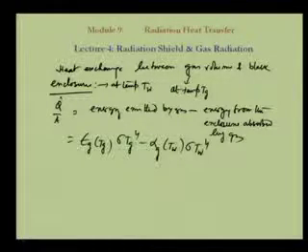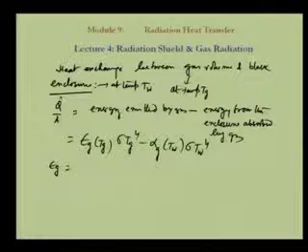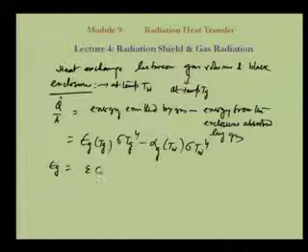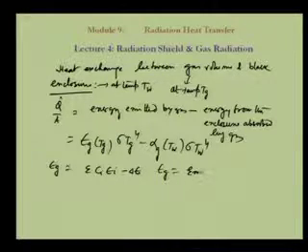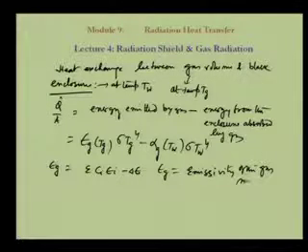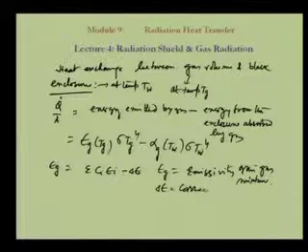Now, emissivity epsilon g is calculated as summation of C I epsilon I minus delta epsilon. What is this? This epsilon g is the emissivity of the gas mixture. The gas mixtures can have different gases with different emissivities. And delta epsilon is the correction for the mixture.